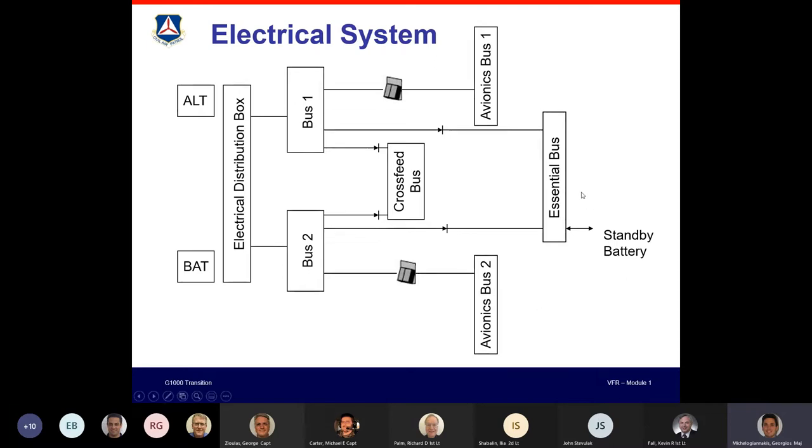But as a little quiz, let me ask you, do you have flaps on the essential bus? Nope. No flaps. That's why I like to practice no flap landings. Do you have any sort of lights? No. The only light you have is the standby instrument lights. But otherwise no lights. So you're invisible to other planes, especially at night. No transponder. You don't have the MFD either, you're just stuck with the PFD. You only have COM1 and NAV1, no COM2 and NAV2.